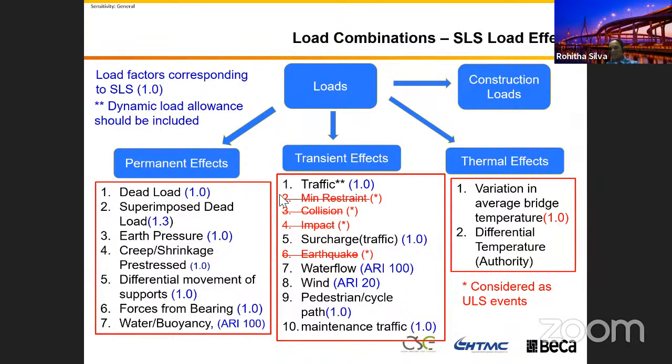But in the Eurocode, it's already incorporated, except in some situations like fatigue. In the Eurocode, my gut feeling is LM1 is the most common and governing load case, maybe LM2. They all include dynamic load allowance.